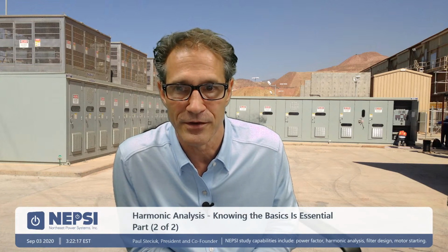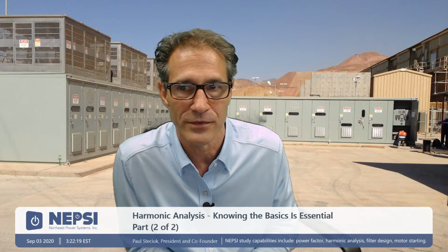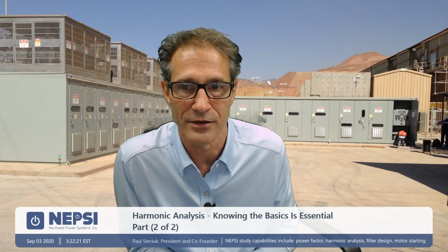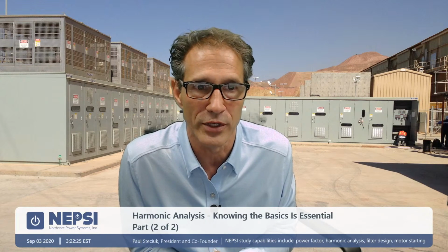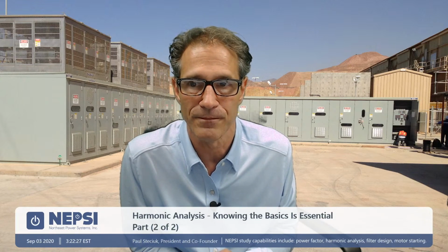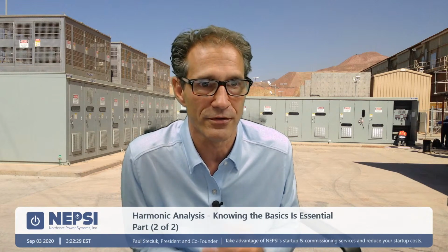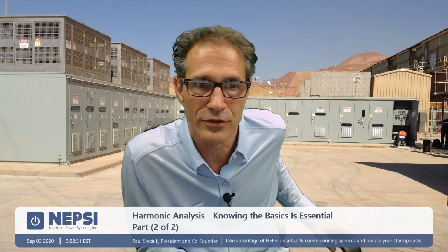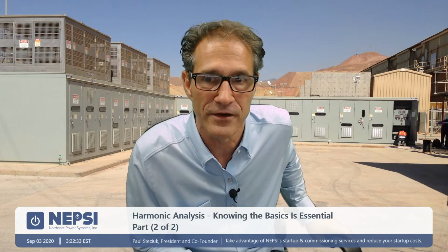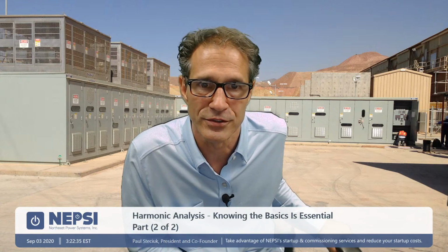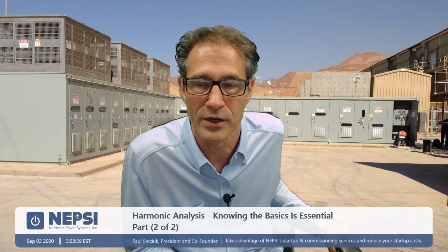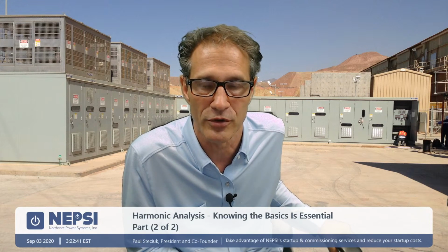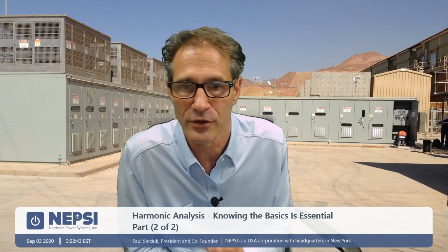Filter banks, a lot of times, are critical to the process that they are being installed on. The system that's actually behind me is an electrowinning plant, and for sure that filter system must run, because electrowinning plants utilize large rectifiers, and harmonic distortion and IEEE 519 compliance will be an issue. So they want systems that are 100% reliable. So we're going to be talking about that next week.